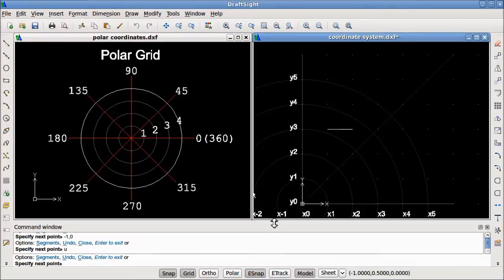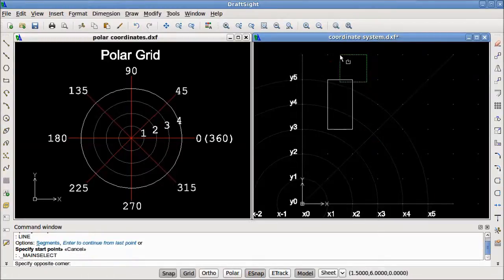And I will finish up this line by drawing a rectangle using relative coordinates. The ampersand 0, 2. Then I will move to the right 1 unit, 1, 0. Then, to finish off the rectangle, I simply need to move down along the y-axis, and I don't need to have any movement on the x-axis. So I will type an ampersand 0 for x and -2 for the y-axis. And now I've closed my rectangle and I can delete this example.